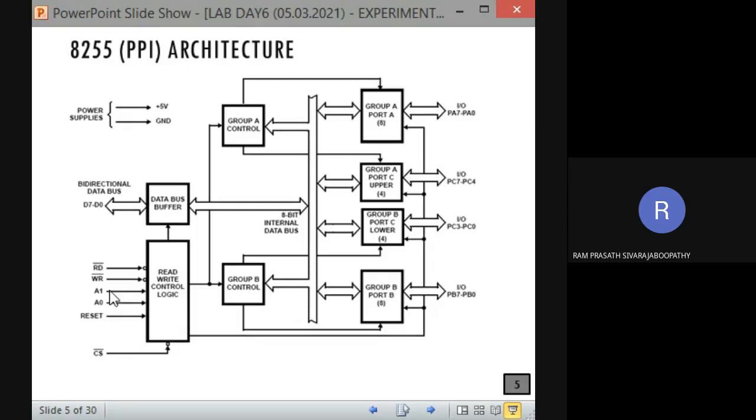Now coming to the point, here we are having 2 pins, A1 and A0. That means how many memory locations can you address? This 6-bit address gets fixed, correct? It is going to select the chip. The 6 MSBs are used to select the chip. Remaining 2 bits we are having. Using those 2 bits, how many combinations of address can there be? What combinations can A1 A0 take?